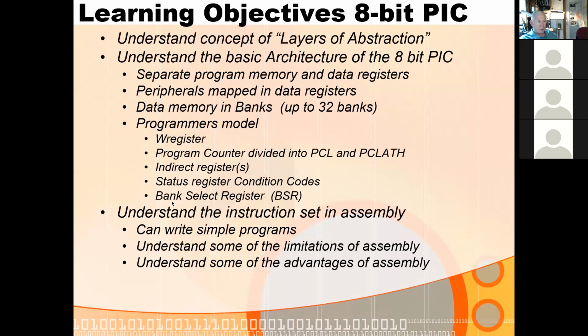It's a simple chip. There are chips that have quite a few registers in the programmer's model. We use Freedom boards for Micro 2, and in Micro 2, there are 13 general purpose registers. On this chip, there's one general purpose register, and it's called the W register, which stands for working register. And we normally just write W when we refer to this.